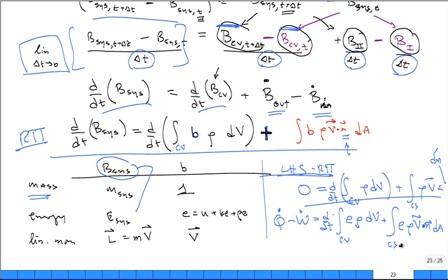Now, you're saying, Professor, how come I don't have enthalpy show up over here? Because I see that's internal energy U right there. Yes, but you separate out the W dot. It has to account for pushing back and being pushed by the boundary work. So you separate that out, put it over, and you'll get the enthalpy.